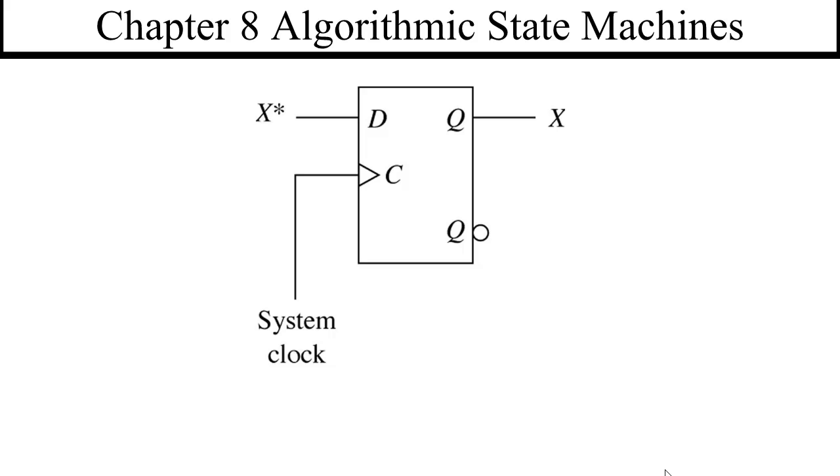The exercise of learning how to design an asynchronous state machine and then applying those design rules to a synchronous state machine enables that synchronous state machine to be clocked faster, to survive more of those glitches before it falls apart. So the next step is to study asynchronous machines and their design rules.